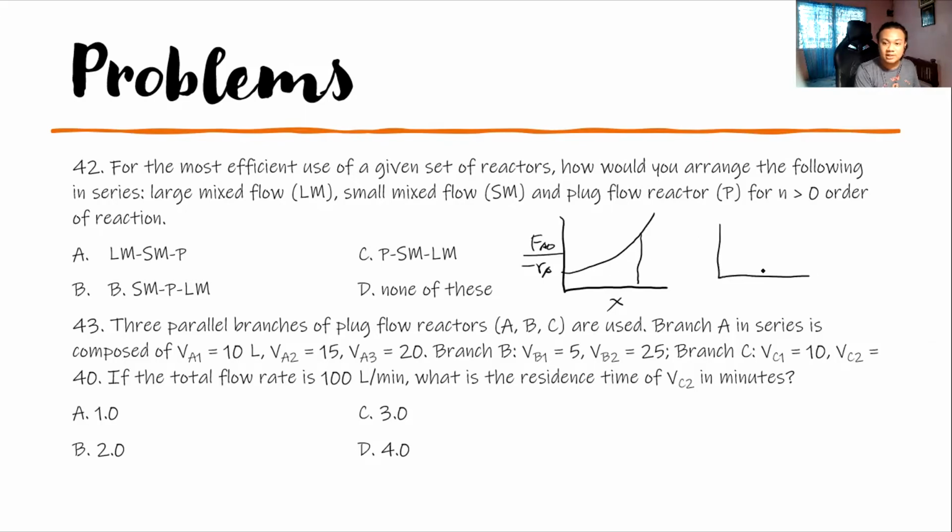And then for a CSTR, same conversion, but its volume for the same conversion is this whole rectangle.